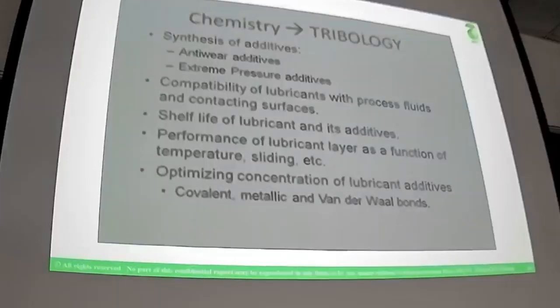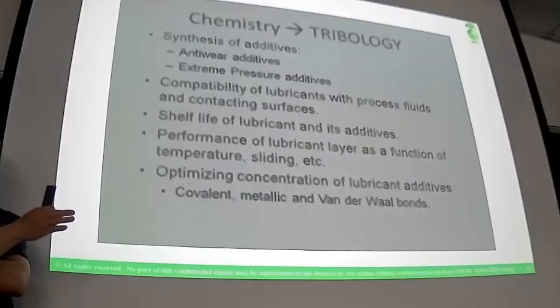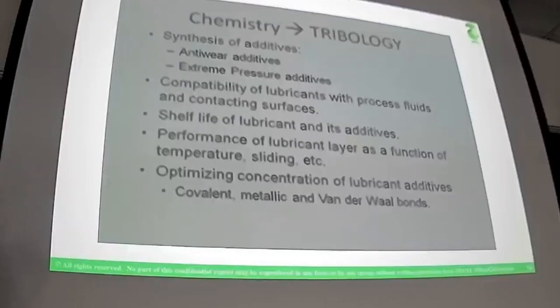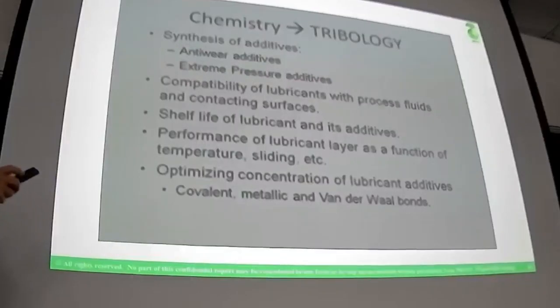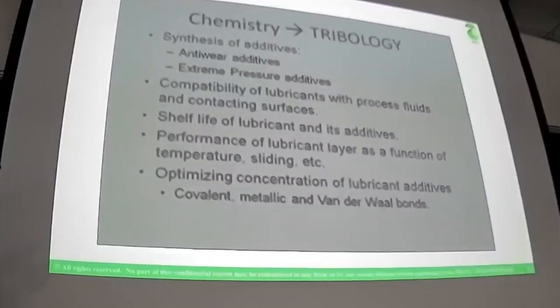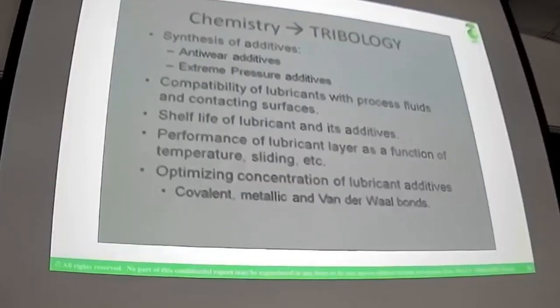For instance, if you are using it in an extreme high pressure condition or environment, your lubricant should add some EP, extreme pressure additives. Okay? Or if you are using your lubricant in a very high temperature environment, you should add specific additives for that.